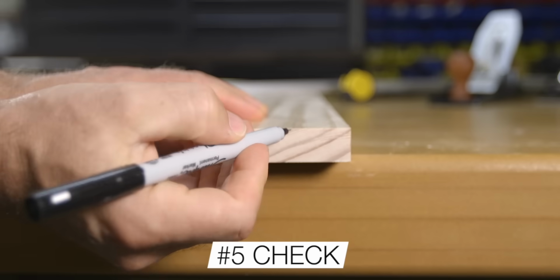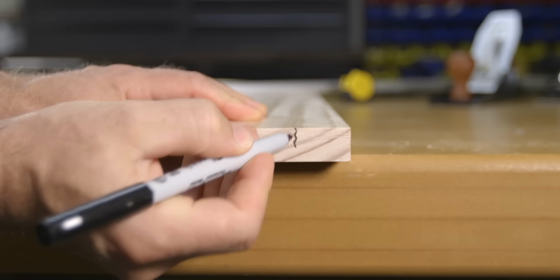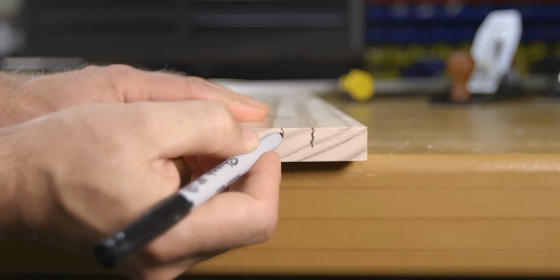Number 5 is a check. A check is when the board or lumber has a crack, but the crack doesn't go all the way through the thickness of the material. And number 6, similar to a check, the split is when the crack goes all the way through the material.